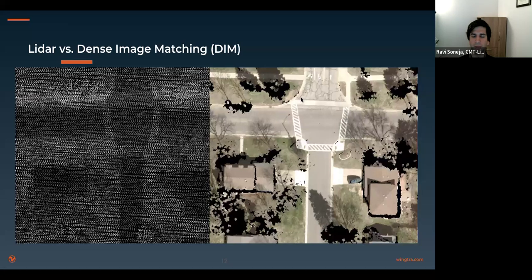No, it does not. When we did our collect here, and anytime we do LiDAR acquisition, the preference is to have a local base running. It's just doing static observation at a 1 second interval. Started about 15 minutes before the acquisition begins, run it for about 15 minutes after the acquisition ends.